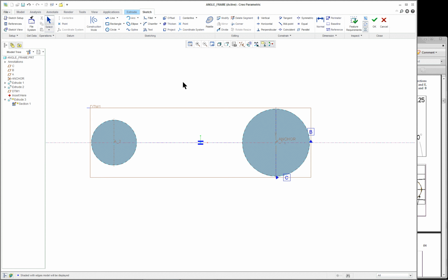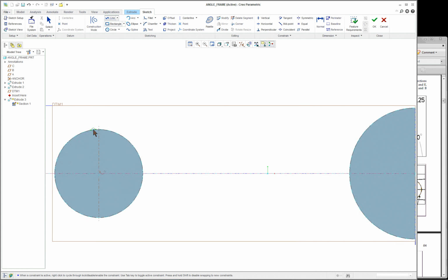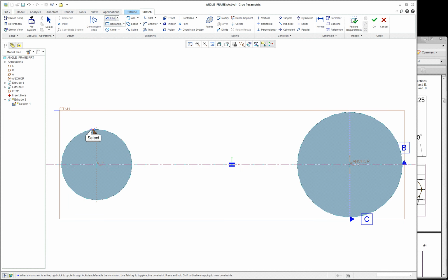Got your center line. But we want to connect these two so it's tangent on one side but not tangent on the other side. So we're not going to pick line tangent. We're just going to pick the line chain. For instance, I can put my arc in first. Here I'm just going to put my line in first. Now we know that this tangency is going to be slightly on the other side of the 90-degree quadrant position. You can see there's tangent.